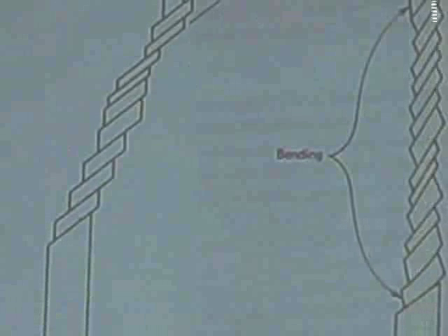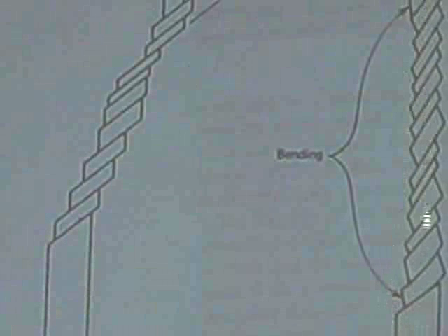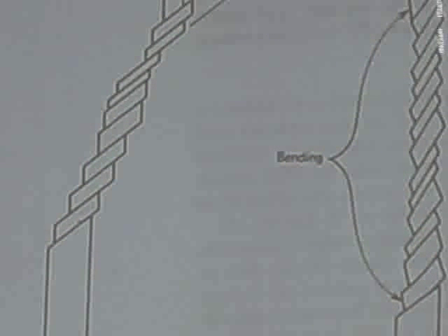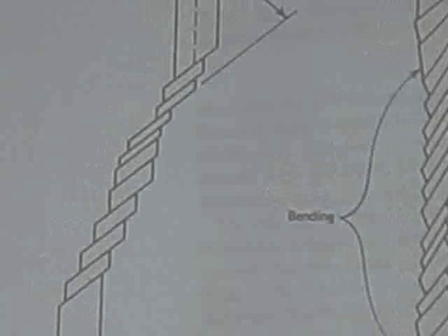In fact, when you actually pull on a bar, a single crystal, you will pull in the same tensile direction because of the stiffness of the machine that's pulling it. And that requires that you also get a bending as well as a shear. Okay? Which you can see here. It's just a nice drawing to show that even a simple tensile test is not so simple.